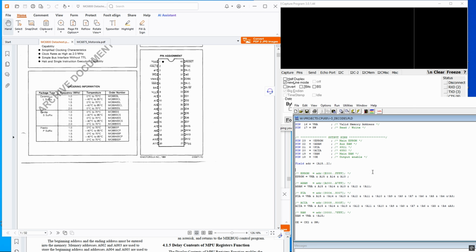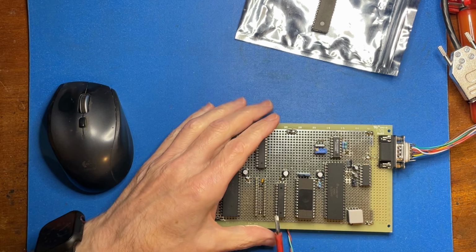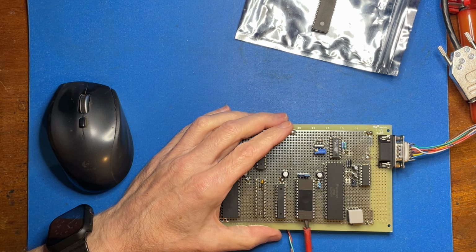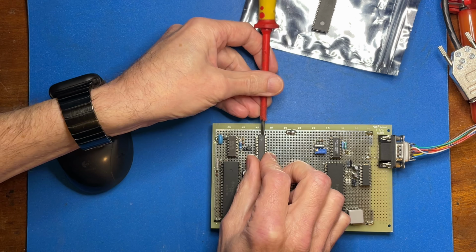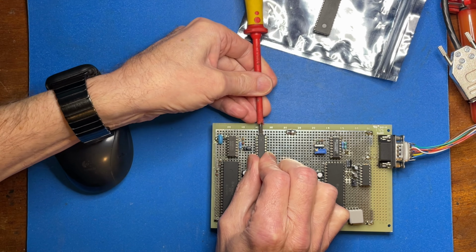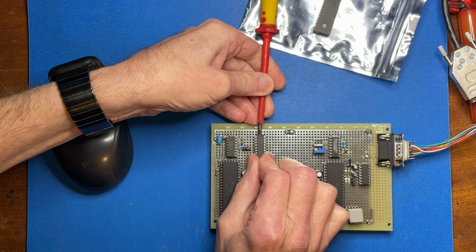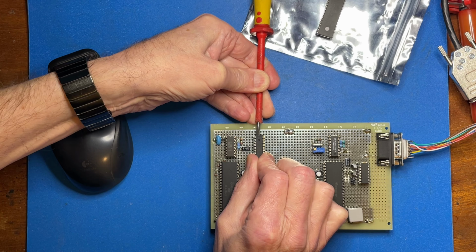So what we need to do now is pull that chip, program the new version, and see if that works better. Because it could be that the memory is getting spurious enables and corrupting it. Not the EEPROM, that. Because it's a very fast memory compared to the original things, and a few nanosecond pulse could be enough to confuse things if the timing's a bit off and it gets a spurious pulse whilst the address lines are changing.